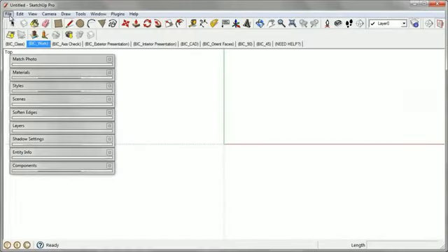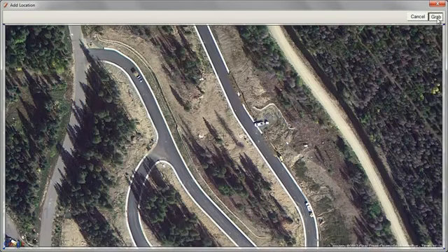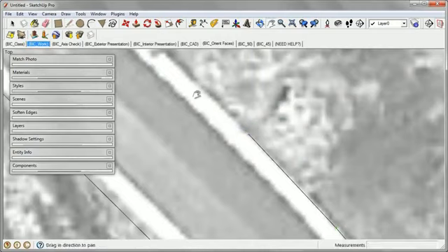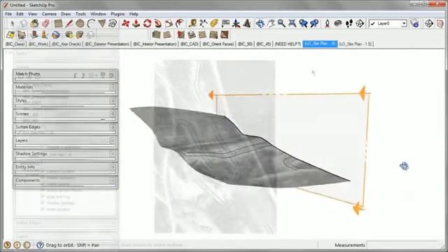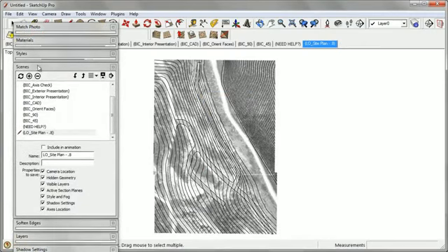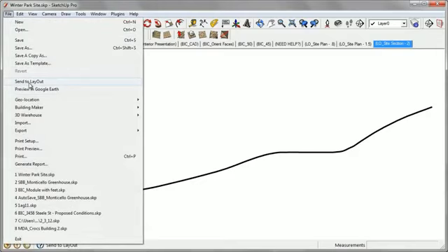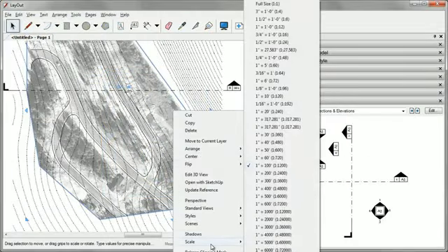During site analysis, use SketchUp to conduct a digital site survey, geolocate the model, collect aerial imagery and 3D terrain, trace a site plan, cut site sections, and generate a topographic survey. Send the model to Layout, the SketchUp equivalent to CAD's paperspace. In Layout, generate scaled diagrams on standard or custom paper sizes. Print.